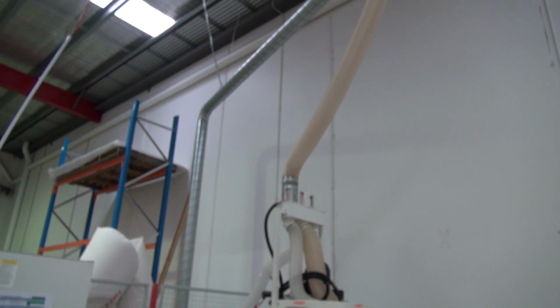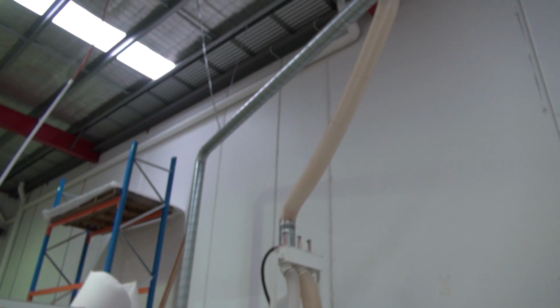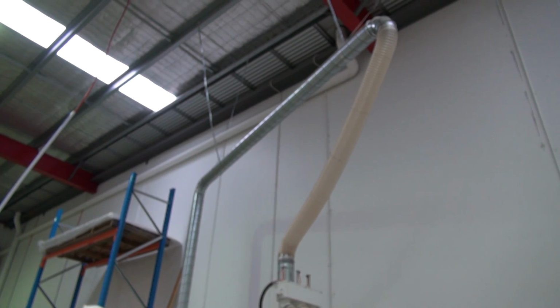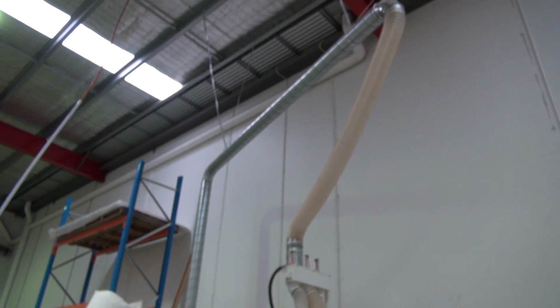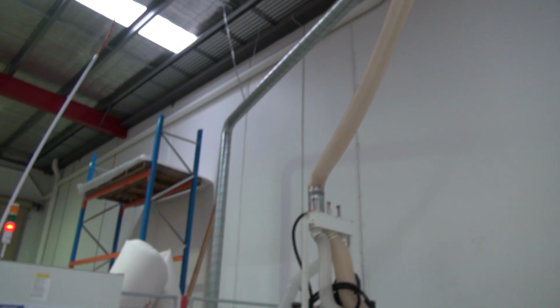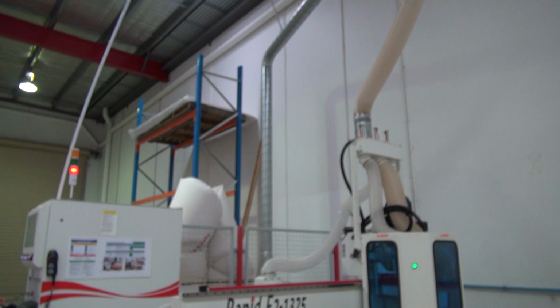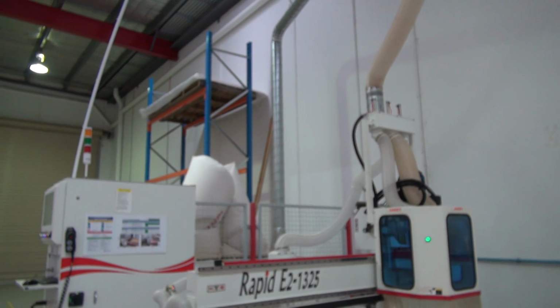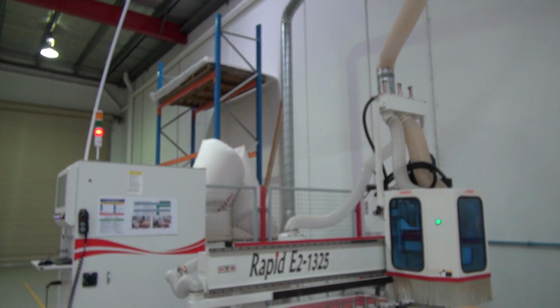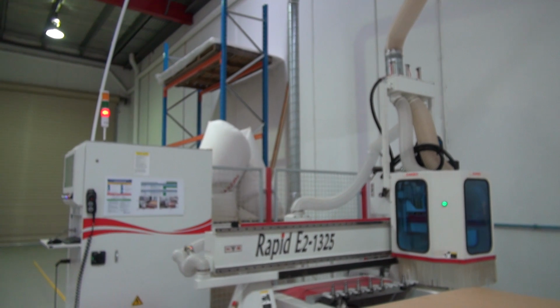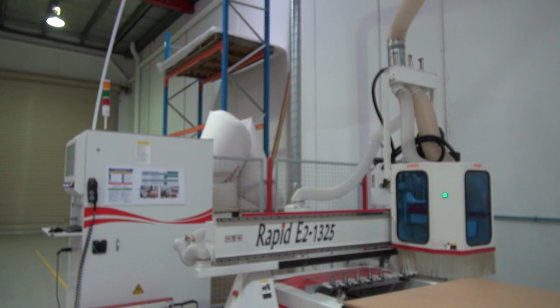The cutting head is the first collection point for the sawdust. It has curtains to prevent dust spreading or escaping. Sawdust then gets transported from the bed or head of the machine through the ducting pipes and into the dust bags. The filters and bags collect the sawdust that is created by the drilling and cutting operation.